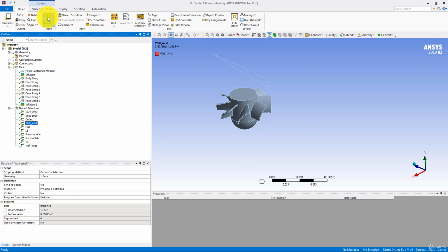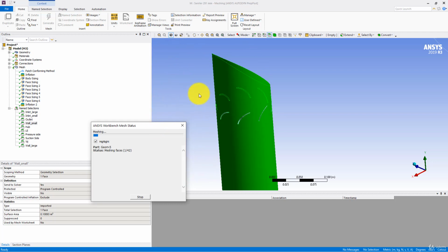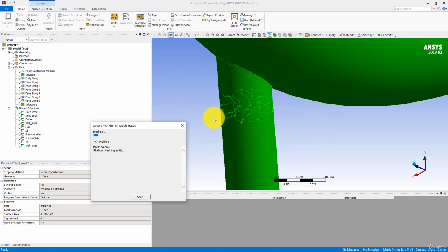So we have to generate the mesh again and see if there is any issue, and if there is, we will solve it. But I think most probably there will be no issue at all in this case because the geometry was intact. We just moved the geometry and it took its shape and location very nicely and precisely. Therefore just wait for the meshing app to finish meshing the swirler with a new location inside the mixing elbow.